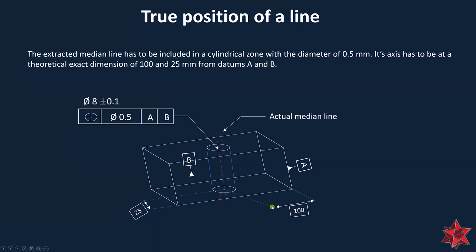Usually a hole, if its length is high, we will see true position on different sections of the hole. So you will see probably from this surface a section right here at, I don't know, 2 millimeters, to see exactly what is the true position at 2 millimeters, because it will have a value, as we can see right here, and at the center it will have another value.